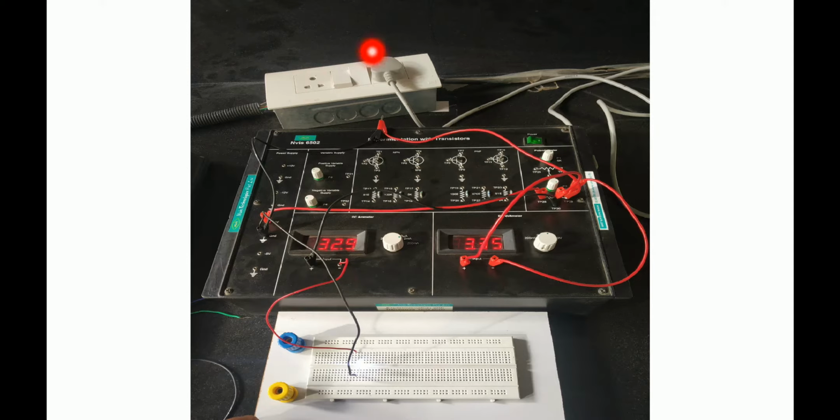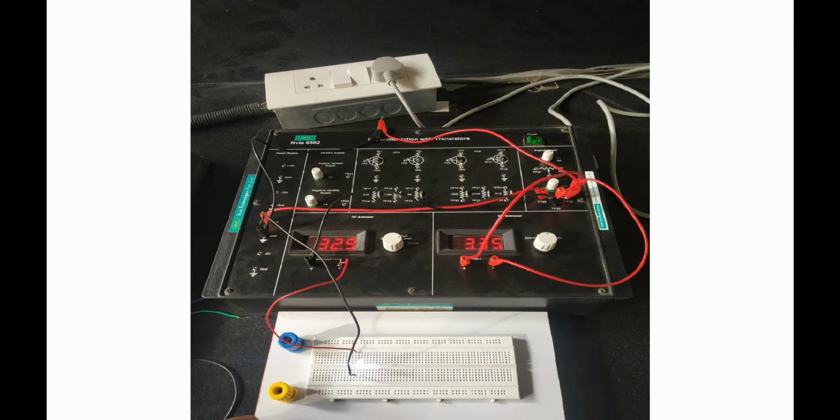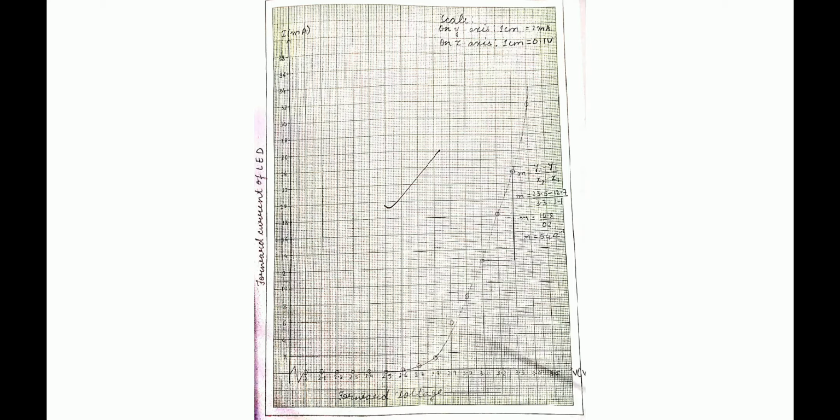Now switch on the power supply. The voltage is set at 2 volts and the current through the LED shown by our ammeter is recorded. With the help of slider of rheostat, the voltage is increased in steps of 0.1 volt. For each setting of the voltage, corresponding current shown by the microammeter is noted. Here, by using white LED, the observations have been recorded, and a graph is plotted of forward voltage versus forward current of the LED. Similarly, take different LEDs and do the same procedure.